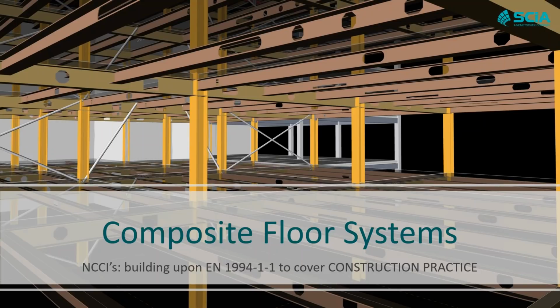Hello, can you hear me? Okay, that's good. So I will present now improvements related to composite design. What we had in version 18 is optimization of composite floors, taking into account possible solutions based on number of studs, cross-section, and adding camber to the beams.